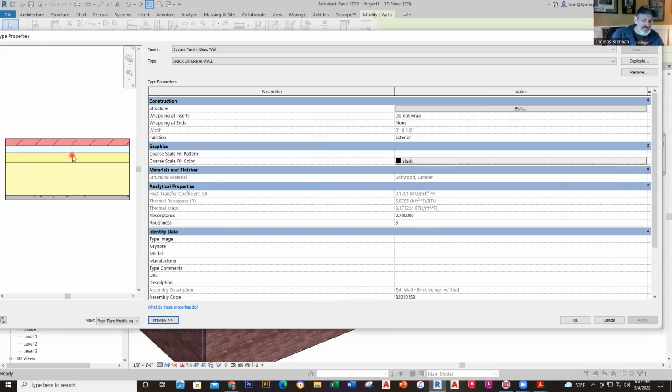So that's what the wall looks like. These are the layers that are part of the wall. You have an exterior brick, it's a brick veneer. When I made this house, like I showed you before, there was about a 3/4 inch brick inset and that went into this blue foam material. And then after that, you had sheathing, and then your stud, and then drywall. That's what the wall consisted of.